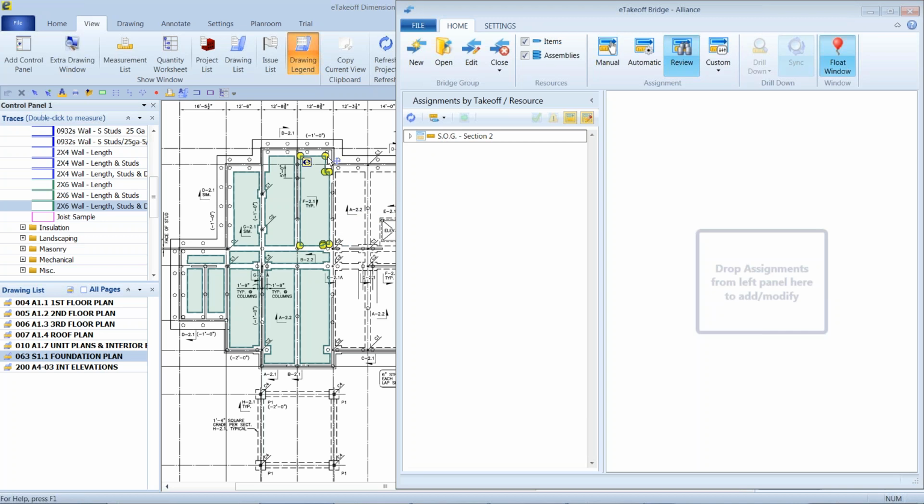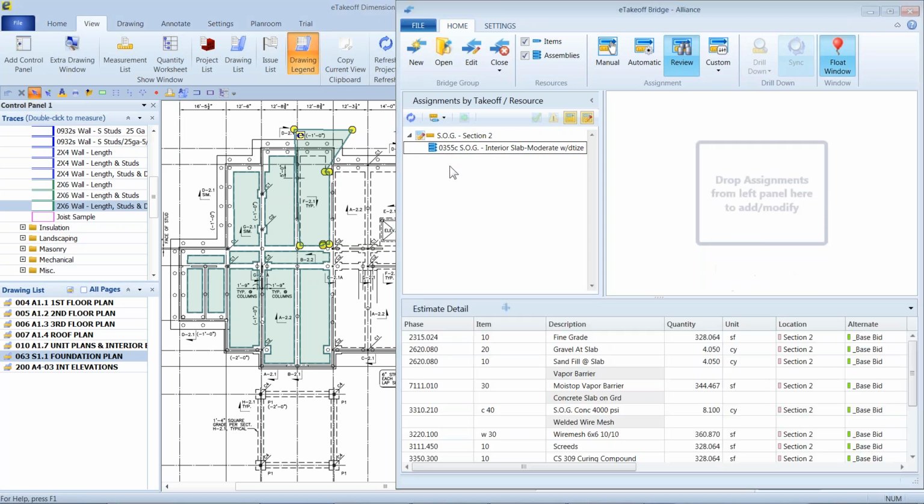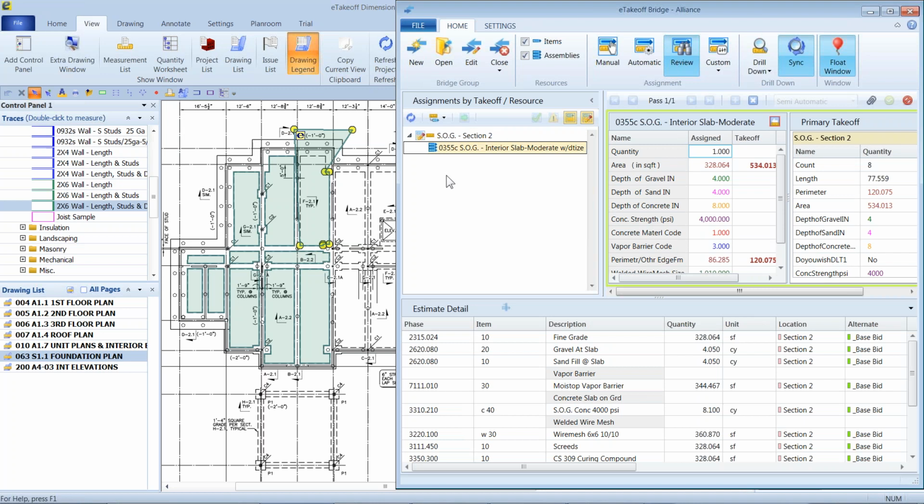Well, in this case right here, for whatever reason, it becomes this. Never know what a customer's going to want, right? So when you look at this, we've got this weird object, this weird slab. If we hit our refresh button here, you'll notice what's changed. It's going to give us a pencil mark right there. That is an indicator that that has changed in some way, shape, or form. It could be a WBS code, and it would still give us that notification. But in this case, what happened was it became a little bit larger. So we've got the area went from that to this. Of course, the perimeter went from this to that as well. So that's going to alert us to that change and give us the opportunity to update the information. So with just a click of a button, I'm just going to put in changed in demo, let's say. I'm going to put a note in here as well.